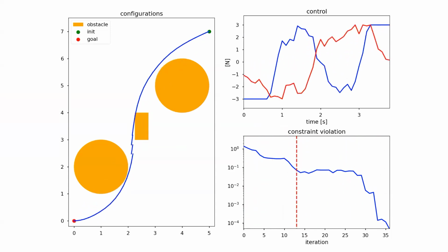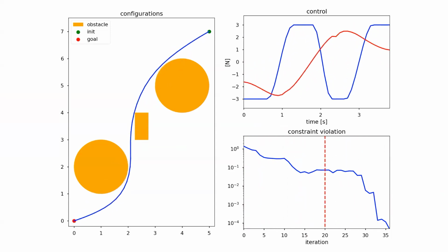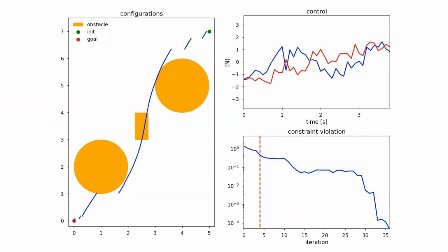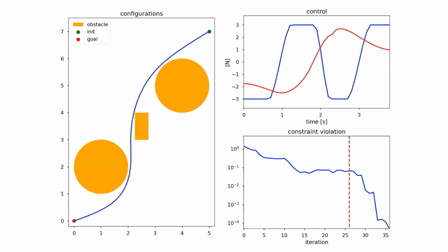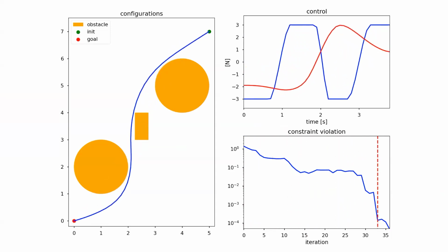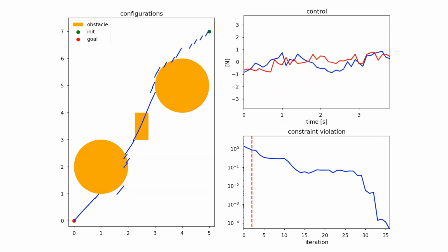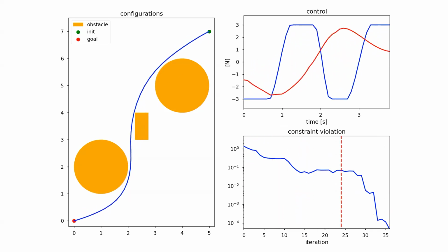And what I do is I use these samples to approximate the constraint function. And I get, again, great convergence in less than 40 iterations. And again, I have control bounds on the control. So you can see that I've capped the acceleration between -3 and +3. So all these constraints that we have in this problem are just natively handled by our evaluations of the constraint function itself.